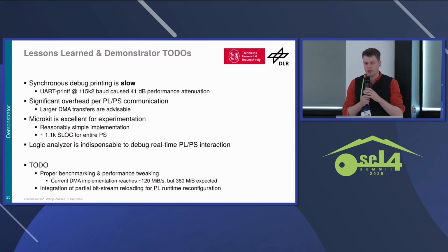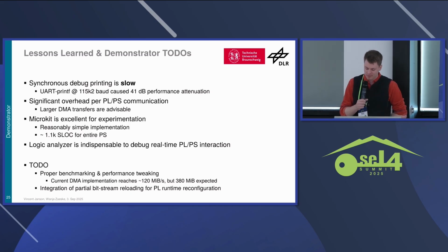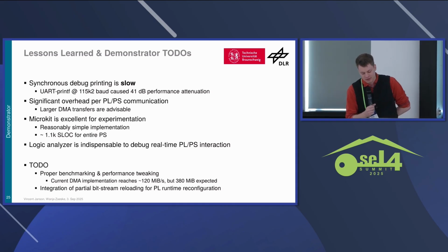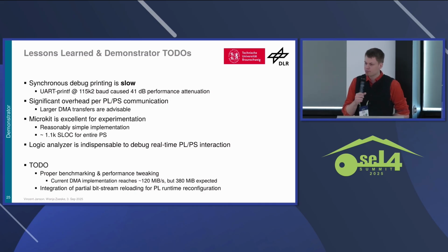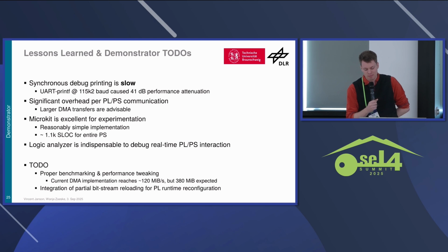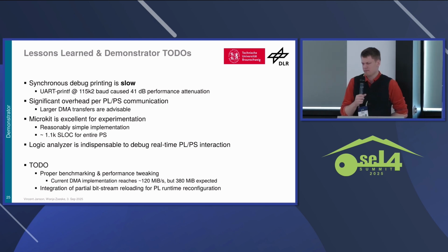We tried to debug the problem until we found out that we had a debug print somewhere that went over a synchronous interface, which was clocked at 115 kilobaud. So that was very, very slow. And once we removed the debug print, the problem really was gone, and performance was better, a factor of 12,000 or something.